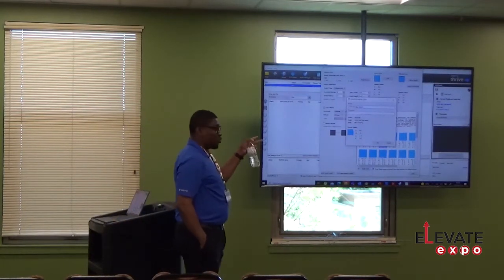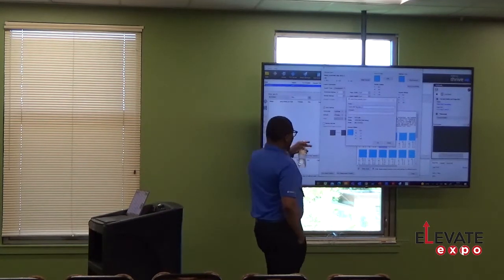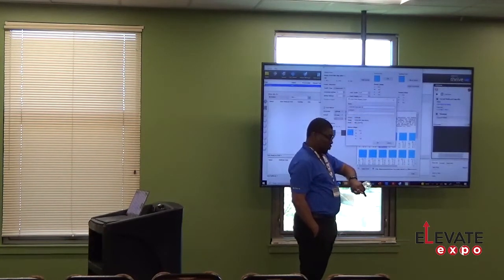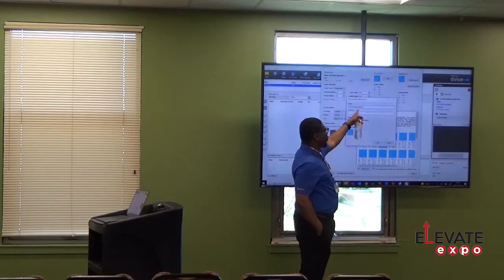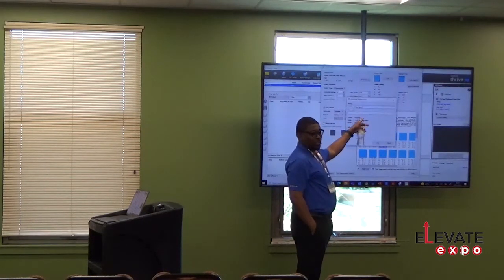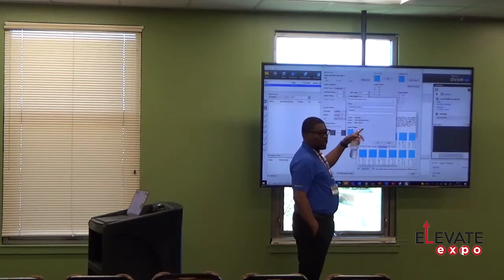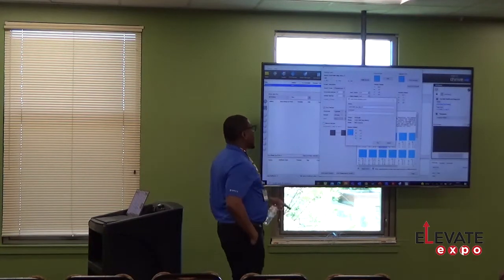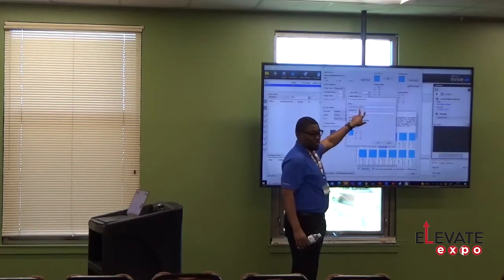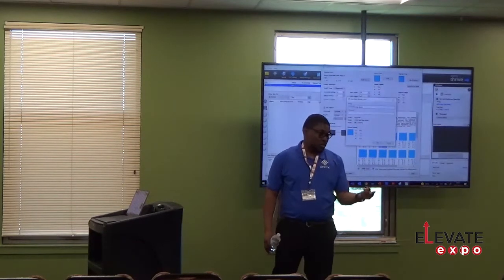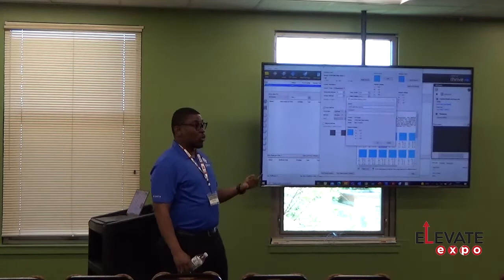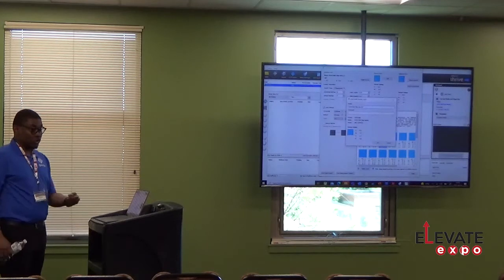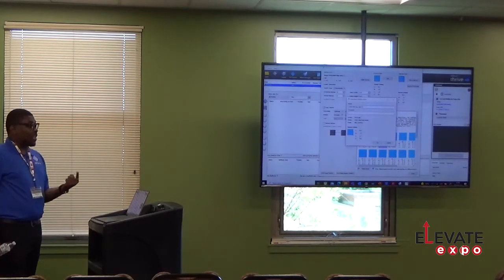We do have, in the software, you could set this. So here we're doing just the print mode, but I will show this more in the tools class because this was split into two. But we have a way for you to set this up to not just affect the specific print mode, and it's what we call user-defined colors. So you can put it where every time a file comes in with this tagged Pantone, it is the recipe you've chosen that replaces it. Now, the reason why we go with the print mode first option is when you do those settings RIP-wide, then you are affecting everything that comes in.